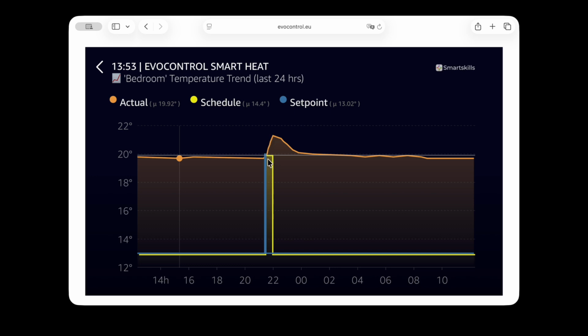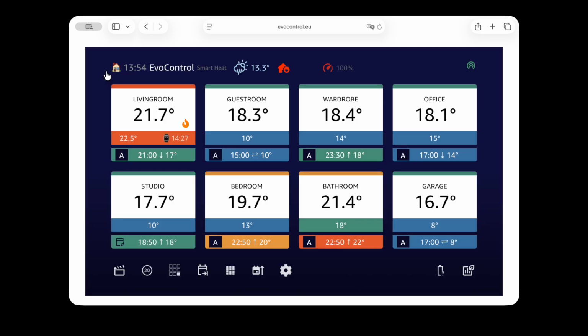And what happened was the demand was reduced as Evohome saw the room heating, and therefore I could learn from graphical information like this that there's actually no need for me to set the scheduled increase in set point this wide, because the system itself will reduce the heat input as soon as it sees the room responding. So this type of information can be very useful to glean from graphs of the system.